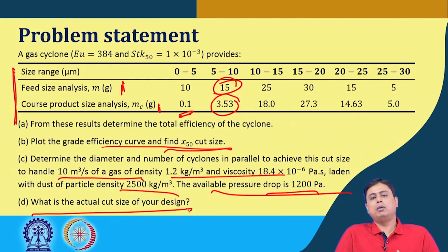and since the number was not a whole number, it was a fraction, we have to take the next whole number to be the number of cyclones, and since the value has now increased, we have to recalculate all the diameter and the cut size, because this would be the new or the realistic values,